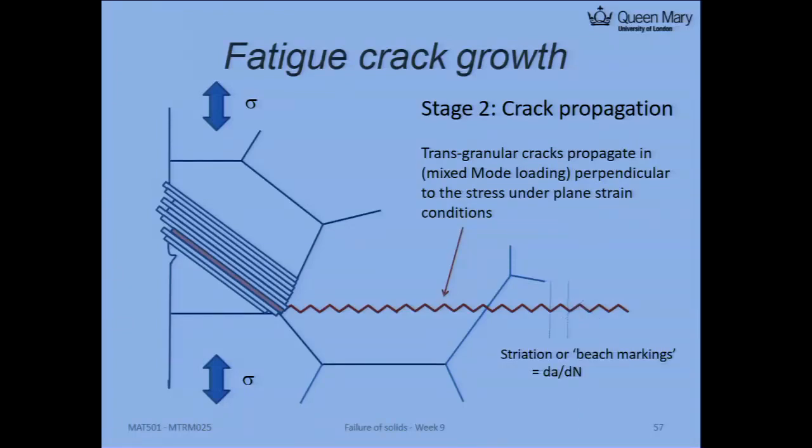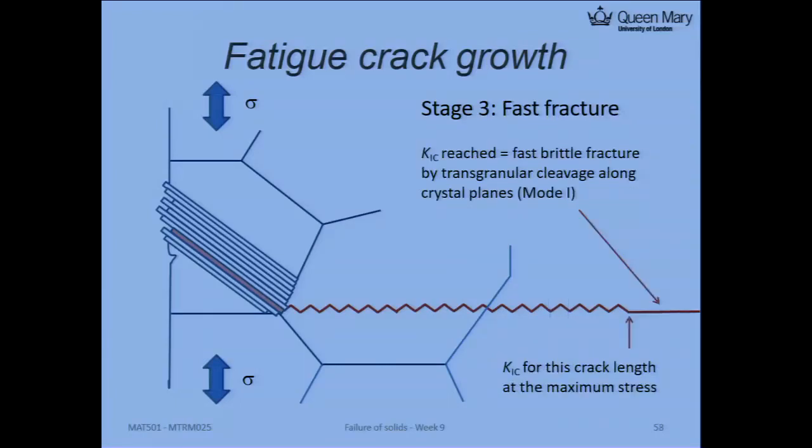And whenever you're looking at the surface, for example here, from left view, you will see this pitch marking. Or you cut somewhere here, it will also give you some zigzag pattern like that, okay? And eventually you will reach some point, the critical point for the material, which is the critical stress intensity factor, where you quantify the fracture.